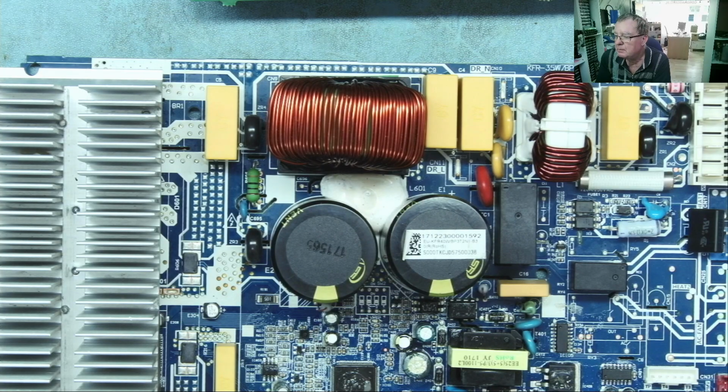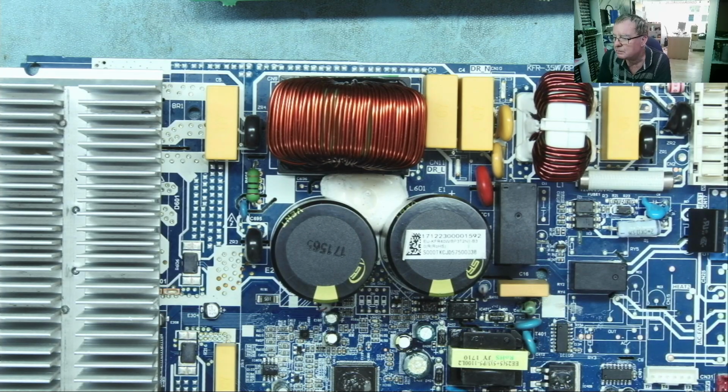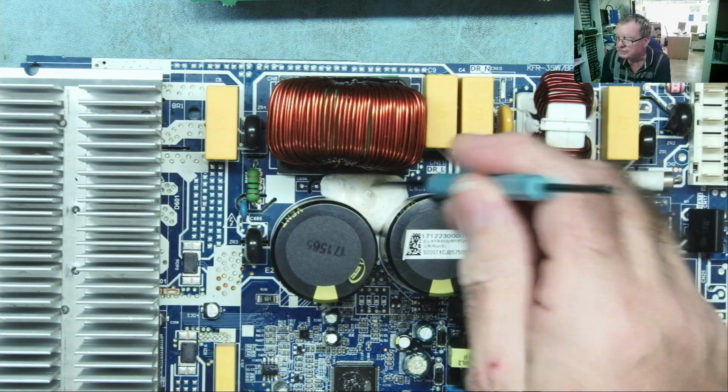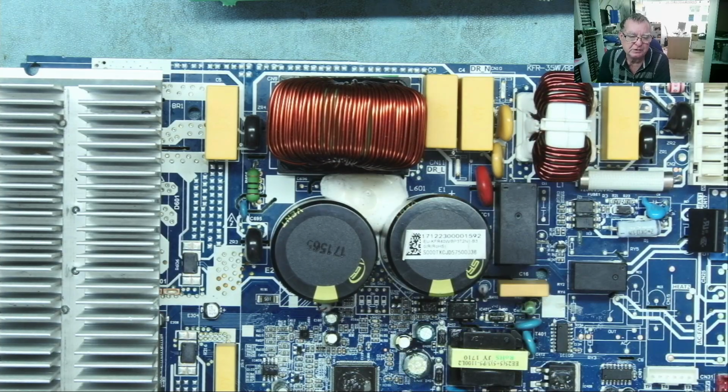Yeah, really you need to get it off the board. So you need to get the glue off, which sometimes is easier than other times. It may have already caused a failure, so you may see burnt out resistors, blown transistors and diodes, burnt parts of the PCB where high voltages have arced through the glue. So glue is something to look out for, and as I say, especially the yellowy beige to brown coloured stuff. This sort, and there's a black sort which is rubbery like this but black, in all honesty don't really cause a problem. If the glue has become conductive, it can cause all sorts of damage to the PCB.